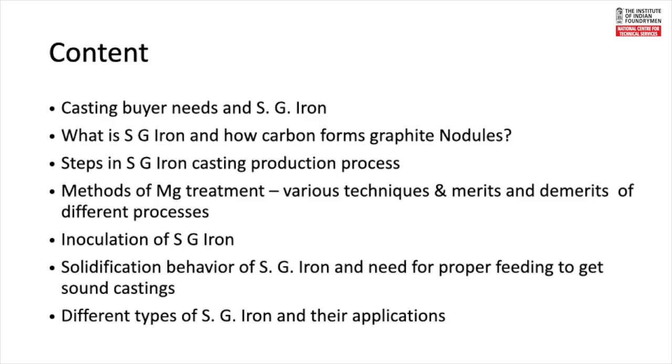Gray iron, very rarely you will require any feeding because carbon which comes out of the solution compensates, because it's low volume, it compensates for any shrinkage which you have. And very, very briefly, I'll talk about different types of SG iron and their applications. So that is what I intend to cover today.